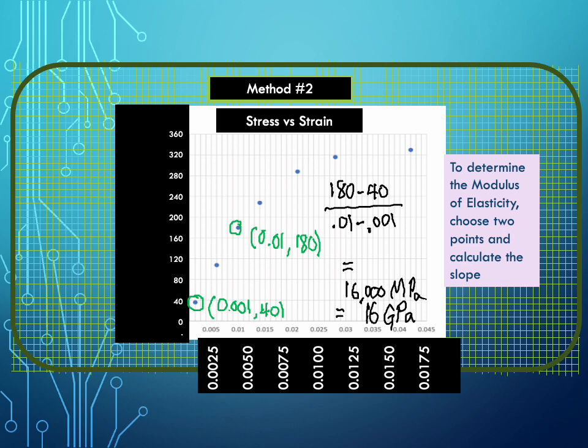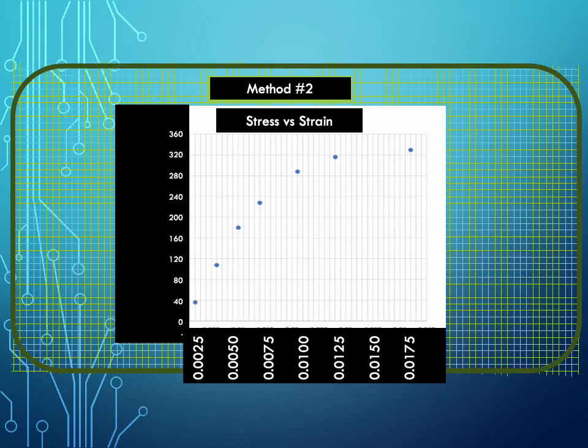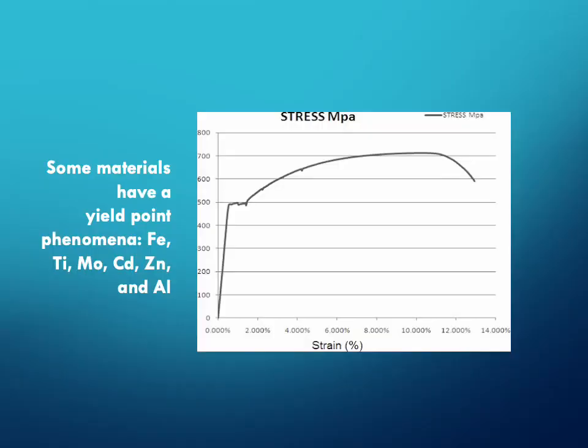All right. And I think I just threw that graph in case I needed one more, but I don't in this case. All right, so occasionally with some metals, we get a yield point. Instead of a curve that's linear and then just continues nonlinear, at the end of the linear region, there will be an extension that does not result in an increase in stress.